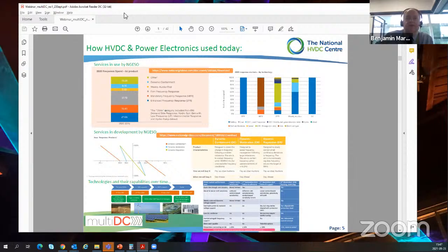So the intent of this is to deal with the symptom, which is essentially that as the inertia is falling, your frequency will move more quickly and it will move more frequently. In any response which is quick, you're going to inject oscillation into that response, which requires a further moderating response to dampen the effect and to manage containment in the latter stages. So essentially the intent of this collection of services is that it allows you to move to still lower levels of inertia, and an ambition to move towards a 96 GVA second level has been expressed.